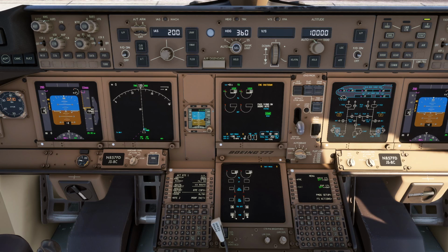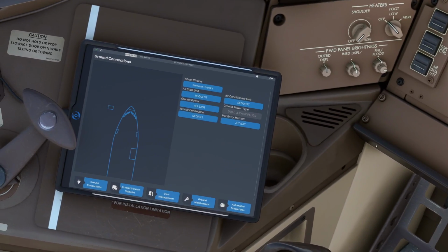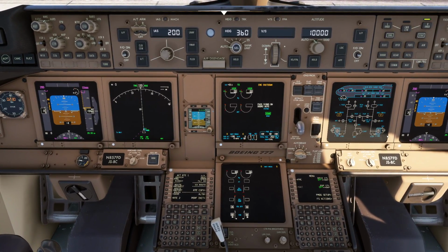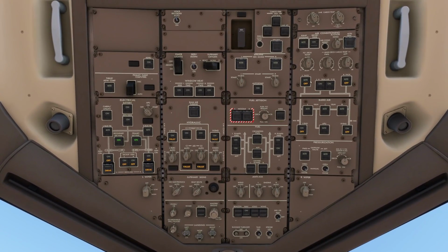How do we supply bleed air? And the answer is an external, it's called an air start unit, an ASU. And you can hook one of those up here. I hadn't done that yet because I wanted to show you, this page shows zero duct pressure, so there's no air pressure anywhere. So our packs are not running, so we're not getting any air conditioning running. So this is expected up here. You see the packs are turned off.